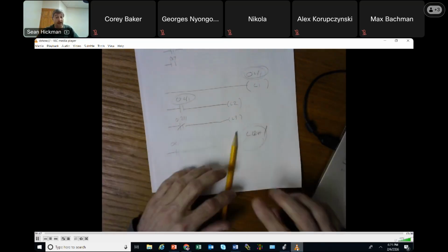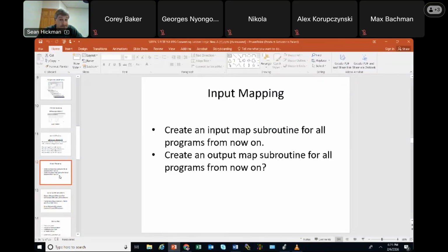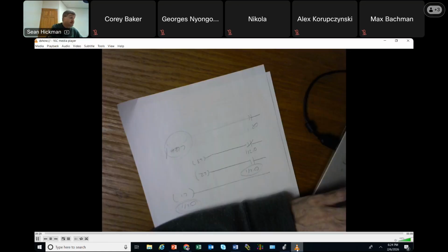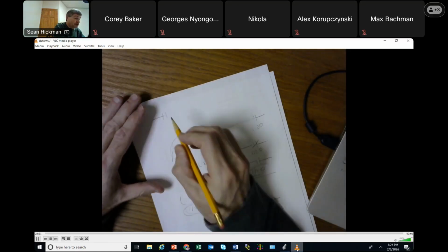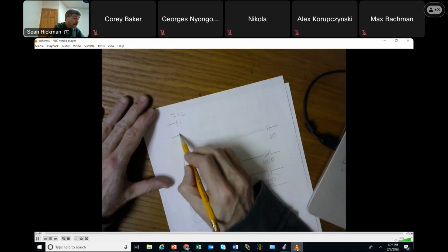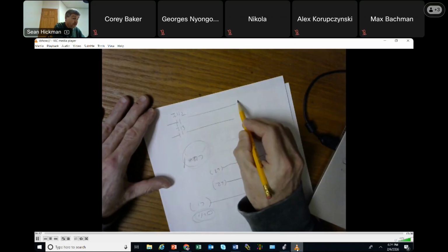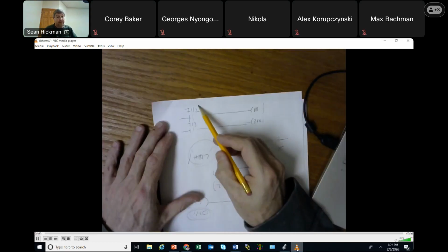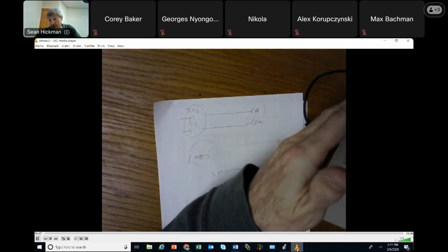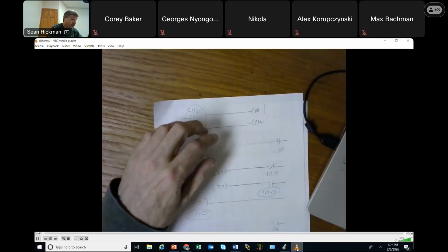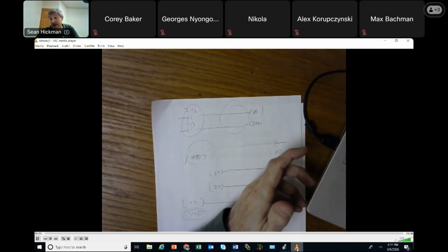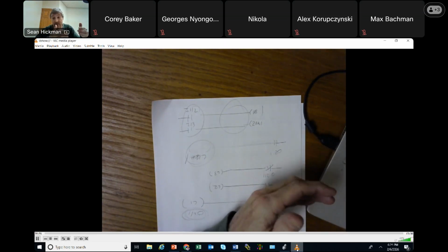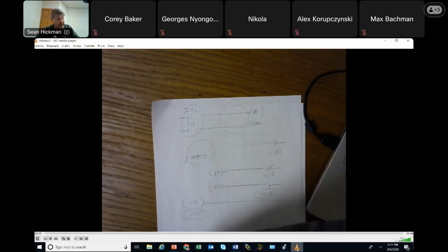Okay. And so when we were mapping the inputs, I just want to be sure everybody understood how that worked. And I'll explain it just one more time. What we did is we took the input, which is I1, I don't know, I'm just going to take some inputs here, I13, whatever. And we call this 1 PB, and let's say this 2 PB. So these get scanned and updated on their own separate scan. The ladder logic here is running a different scan. They are not synchronized. They are not running 20 milliseconds together. They could be running at different scan rates.